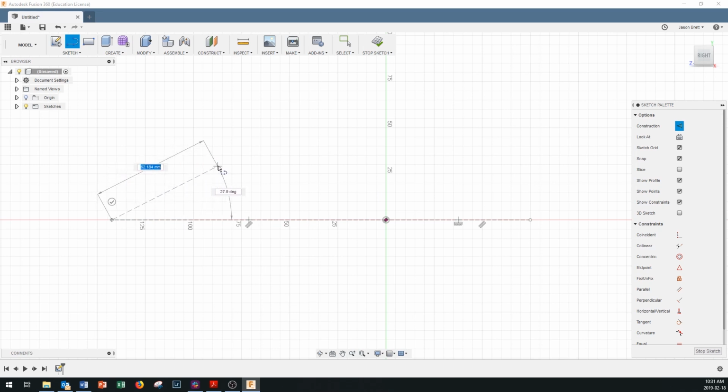We'll have a support node here. We'll have our top node here. And then we'll come down and we'll close off our truss right over there. We'll also have a vertical support coming up right here. And then a couple of zero force members, the members that are holding our support nodes in place, one to right there, and one up to right there. And that gives us the basics for our truss.